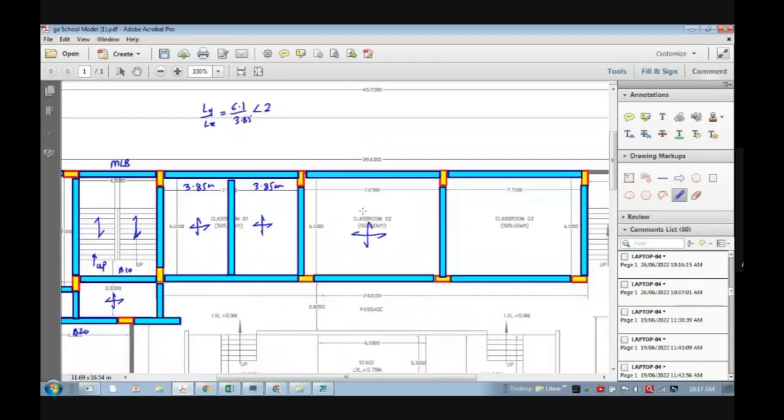So as a choice, see, sometimes architects are not happy with such kind of intermediate beams. So they say, can you provide without beam? There will not be any problem. So see, there is always a debate between the architects and the structural engineer. But whenever there is a structure like school buildings, college buildings, or public buildings where the aesthetics we can avoid, we should give more focus to the safety and serviceability of the structure than the aesthetics.